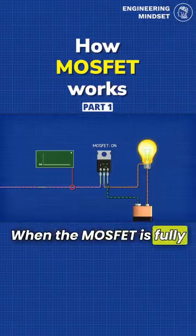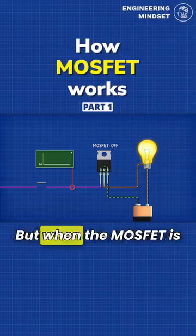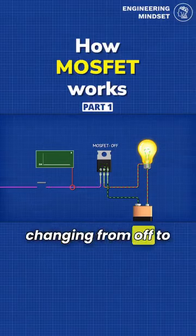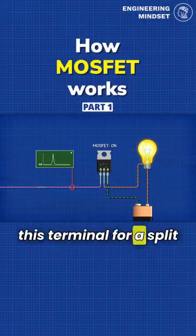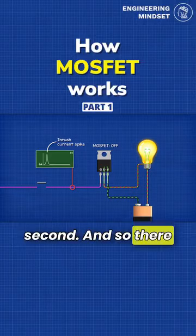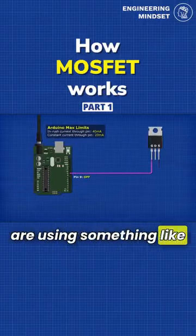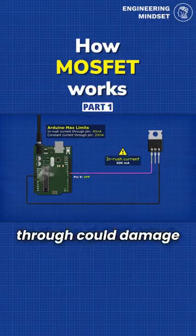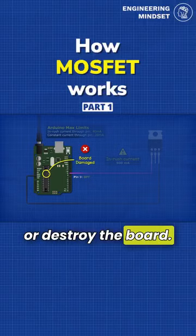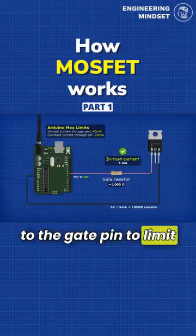When the MOSFET is fully on, no current flows on the gate terminal. But when the MOSFET is changing from off to on, electrons rush into this terminal for a split second. And so there is a large inrush current flowing here. If you are using something like an Arduino to power the MOSFET, the current passing through could damage or destroy the board. So we need to add a resistor to the gate pin to limit the current.